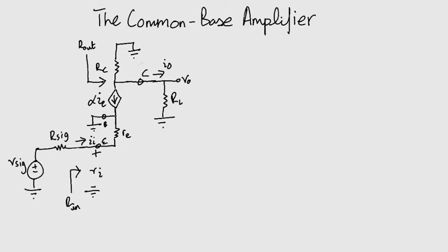Now notice that RC and RL are in parallel. Why? Because CC2 has been assumed to be short-circuited. We again analyze this in the same way that we did the common emitter amplifiers, and we start with Rin. As you can see, it is simply Re. This is because the other terminal of Re is connected via the base to the ground.